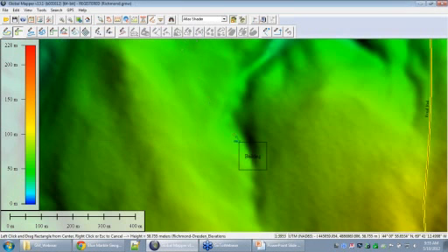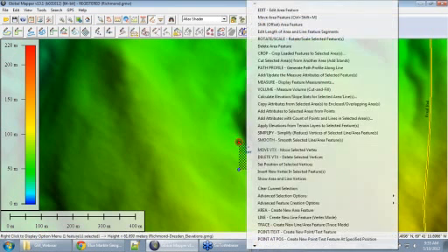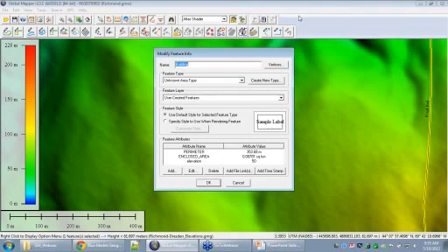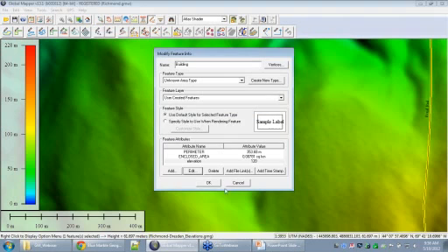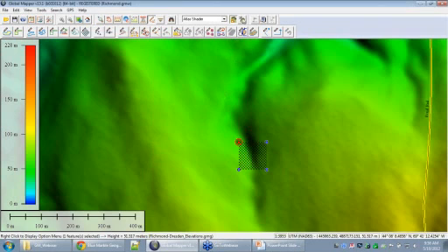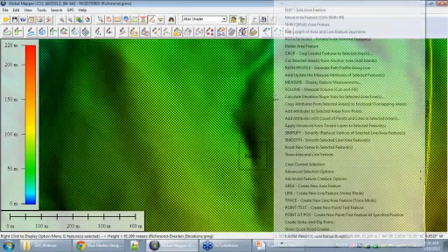So if I want my building to fall into a higher elevation, I can also specify that with a very specific absolute elevation. That's simply by right-clicking and editing on that selected feature, and I can change that elevation. So let's change that elevation to an absolute elevation of, let's say, about 120 meters off of the sea level height here. So I can apply that elevation.